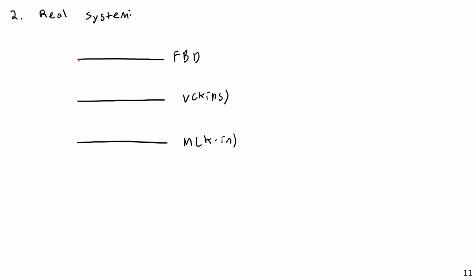So our free body diagram, it's very easy to find the reactions. The left-hand side reaction will be 12 kips. We'll have our 18 kip load at 6 feet from the left, or 72 inches. We do need to make sure to do all of this in inches, again, to maintain compatibility of units. So anyway, let's say we have a distance of 72 inches here, and a distance of 144 inches here. Again, these are just the distances from previously, but in inches.